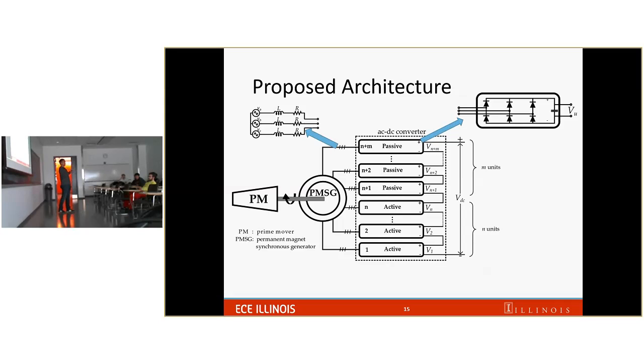It is maybe counterintuitive, but the reason for a diode bridge to be efficient at high voltage and high power is because the diode drop is not dependent on the current flowing through the diode, so it will stay pretty constant around 0.9 to 1 volt. Think about an application with a voltage of about 1000 volt, and the drop across one diode is 1 volt, so you have about 99.9% efficiency on a diode.